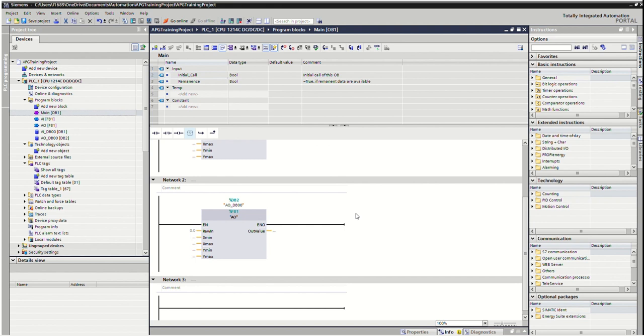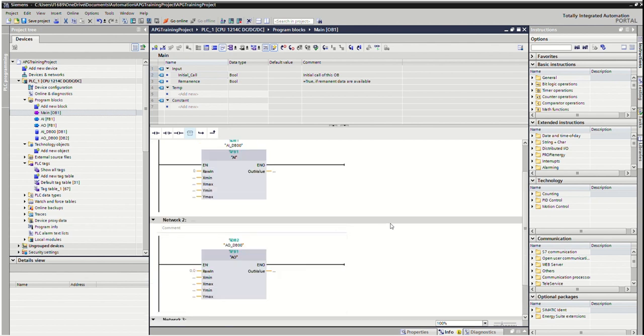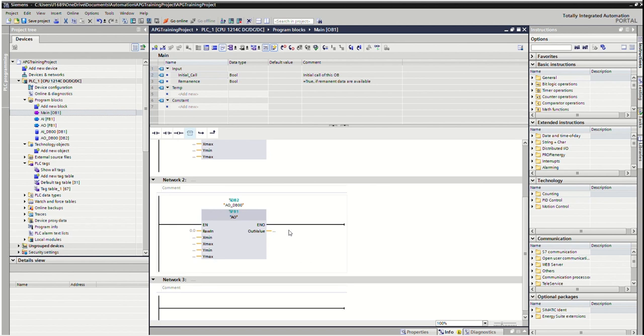So we can create some virtual soft tags. In the soft tag we can move some values that will be just for reference purpose. We can create some soft tags, and from that soft tag we can assign some values to the analog output block, and some raw input is coming for the analog input block.